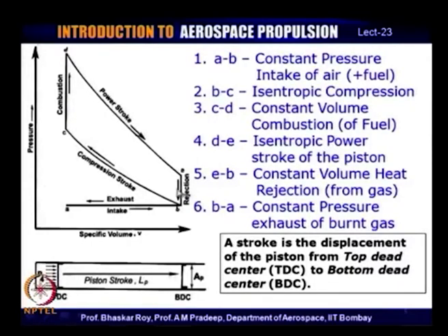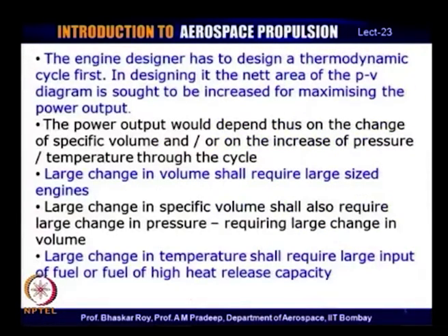Okay. Now, if you want to increase this volume, there are two or three simple ways one can do it. The length of the stroke, so to say, can be increased, by which you can increase the volume. Or the difference between the compression stroke and the power stroke, this vertically, can be increased, which requires that the point D is raised to a higher level, and the power stroke occurs at a higher pressure and the compression stroke occurs at a much lower pressure. So, those are the ideas by which the cycle can be designed to maximize the power output from this system.